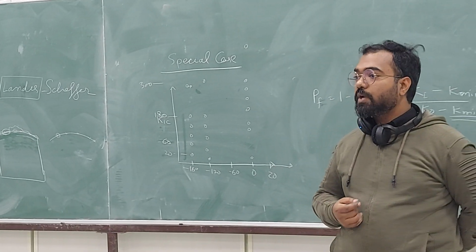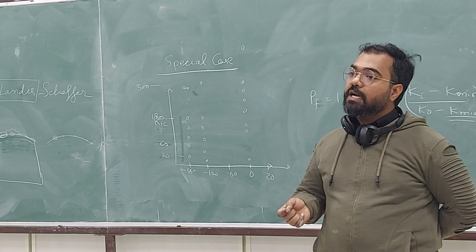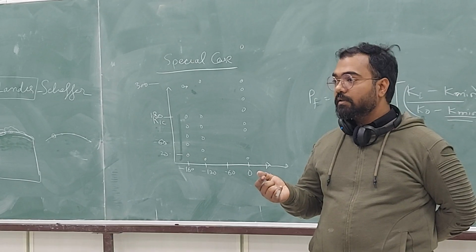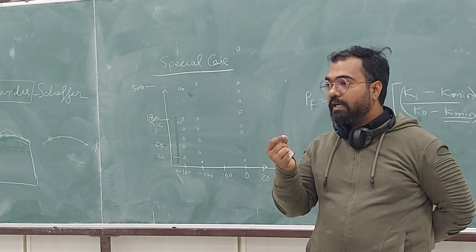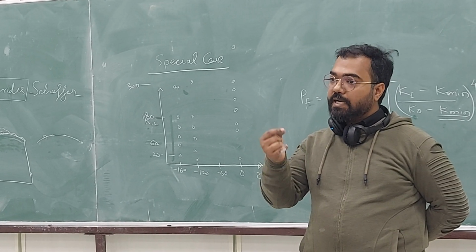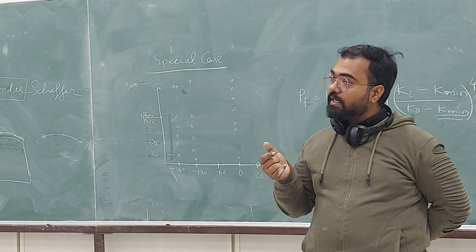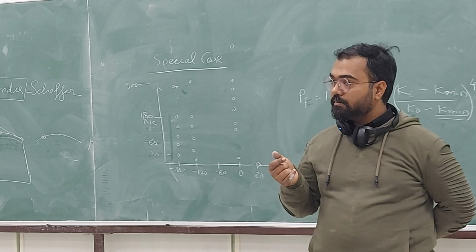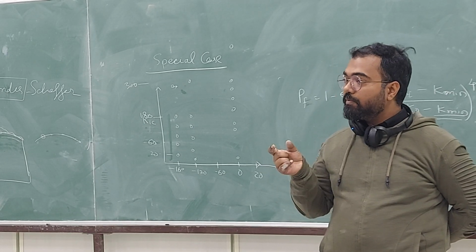Okay? If you have a grain boundary and you have Cr23C6 type carbide, then those carbides have a tendency to nucleate and grow, so precipitate, at the boundary. So that's really not that random. That should be a function of grain size.